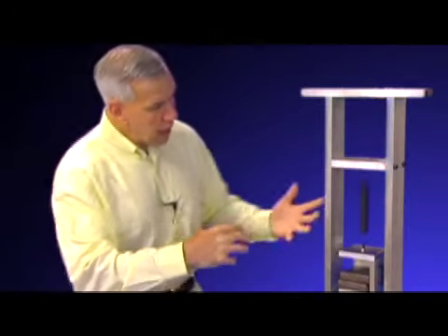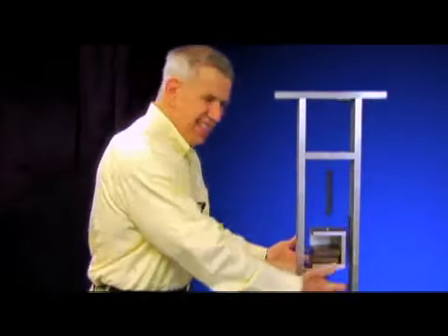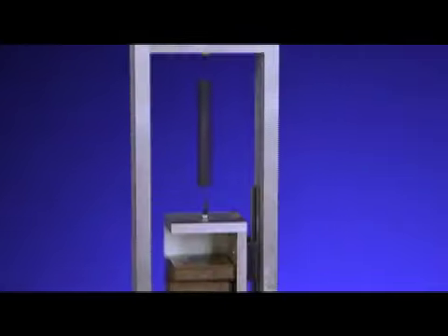Another assumption is that gravity acts straight down and is constant for my location here in this laboratory. Also, I assume that any of the physical parameters of this system, the mass, the spring constant, the energy dissipating characteristics, however I quantify them, don't change with time, don't change with temperature. Do they? Well, of course they do. But for the duration that I'm speaking about and I'm considering, they don't. These are the simplifying assumptions that then lead me to the physical model.